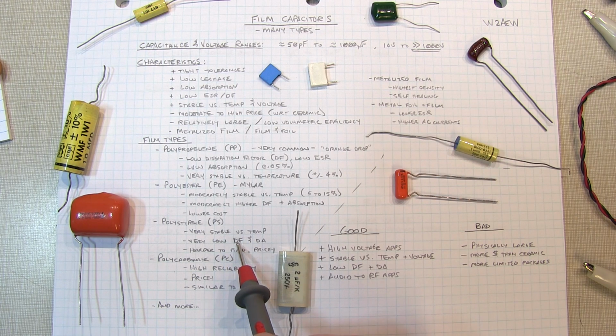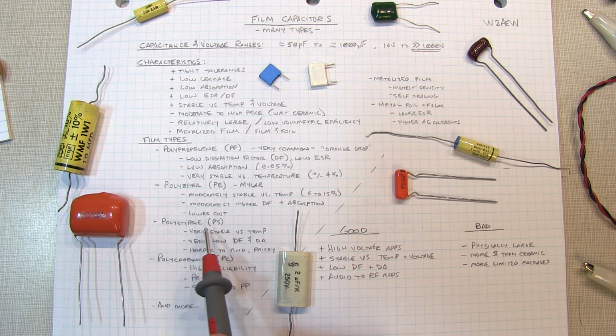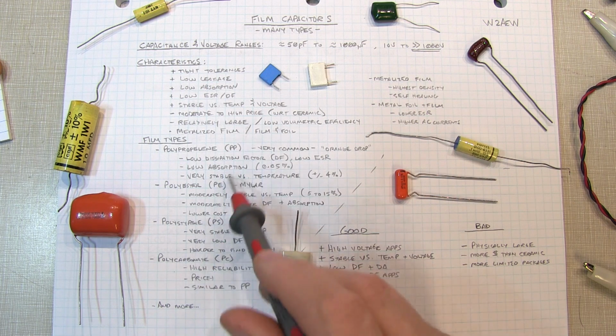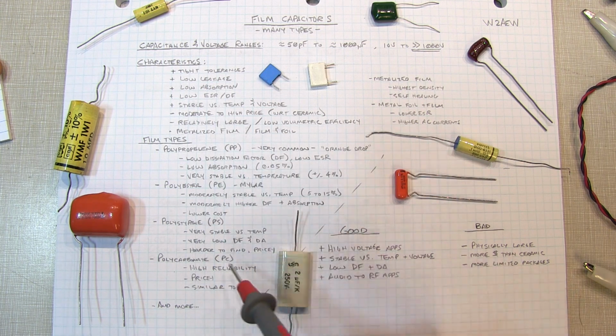They're not really good in very high temperature environments, like next to a vacuum tube or some power resistors, because the polystyrene plastic itself will begin to deform and melt. But in low power applications, they are actually pretty superior to some of the other films. But they are harder to find, and they're a little bit pricey.